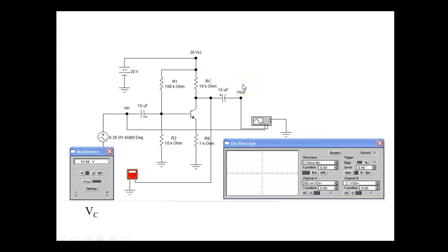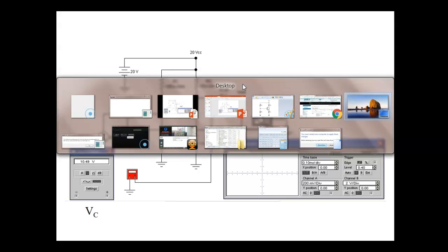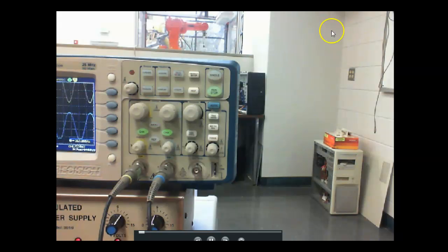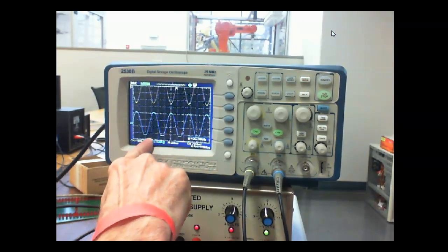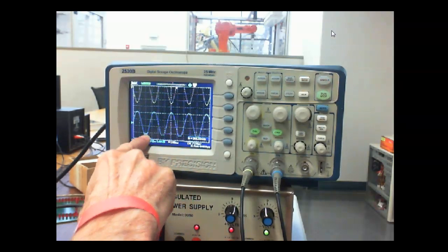So if I overdrive my circuit, it's going to give out a distortion, because my input signal is either going to be high enough to saturate it or low enough to cut it off, right? I think I told y'all, since the output is 180 degrees out of phase, if it clips up here, it means it's saturated. If it clips down here, it means it's cut off.